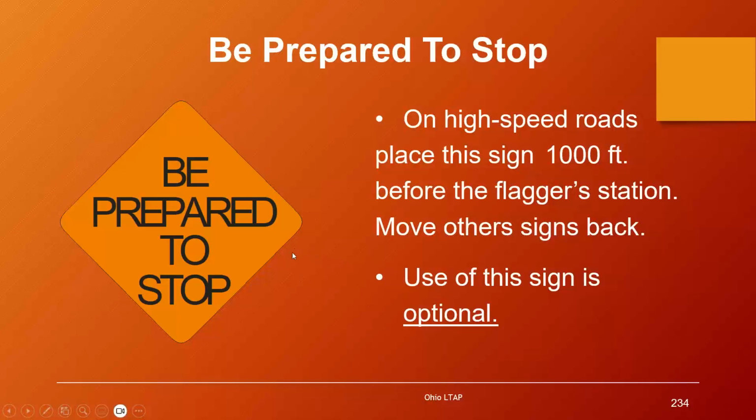But you might recall that I called the standards, guidance, and options, I referred to them as safe, safer, and safest. But ODOT crews are trained to always use the be prepared to stop sign in their sign series. So they always put out 4 signs. And that's because ODOT crews are always working in roadways. Our 2-lane state highways are all high speed, and some of them have high volumes or sight distance restrictions.